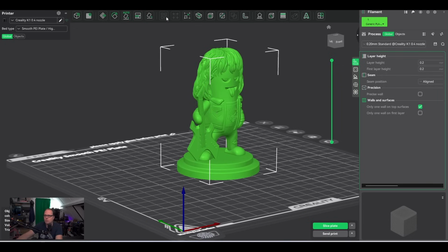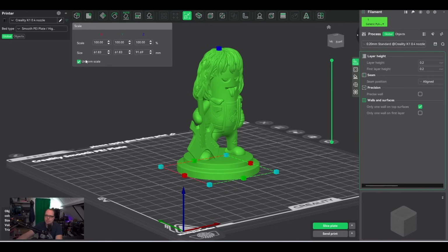Then we have here some other ones. These are not selected, split into multiple objects. We don't need that. We can also scale here. It's always selected on uniform scaling. So if you are selecting it for being a little bit higher than 9 centimeters or 91 millimeters, as we always say it in the 3D printing world, you can also go higher, like maximum build volume, maximum height of your 3D printer. Never go over it, because you get a flat head and you don't want to have a flat head. You don't want to look into somebody's infill. Let's say it like that.